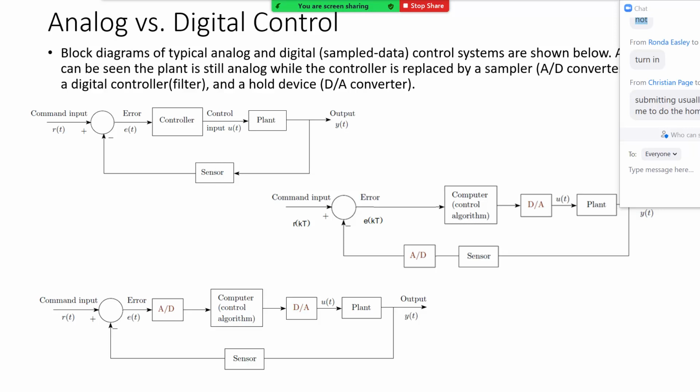So these are the 3 things that we're always concerned about when we talk about a control system: the transient response, how fast the system responds, and the shape of that response. And if you remember, when we studied linear control, we looked at the second order system because it showed us all that behavior. It shows us the overshoot, the oscillation before it reaches a steady state, the rise time, the settling time. All this is part of the transient response.